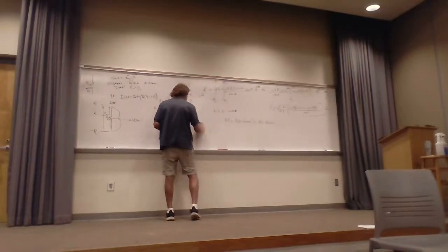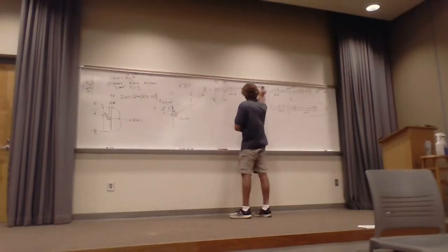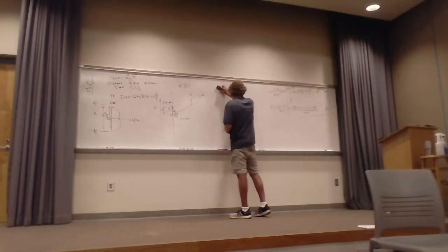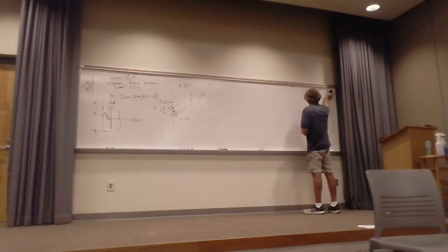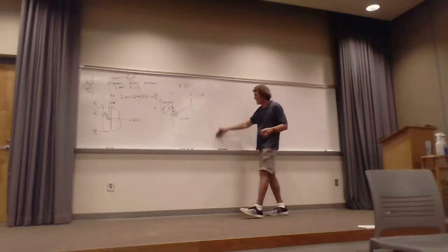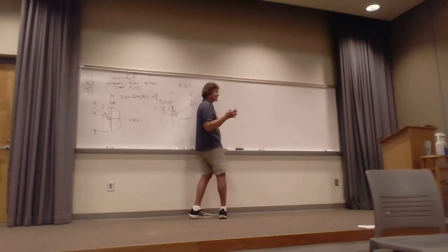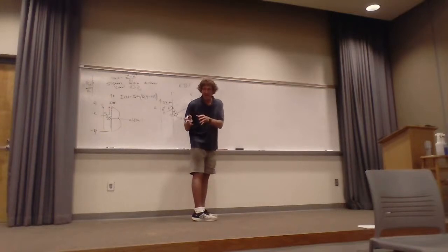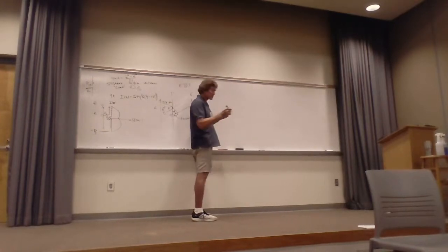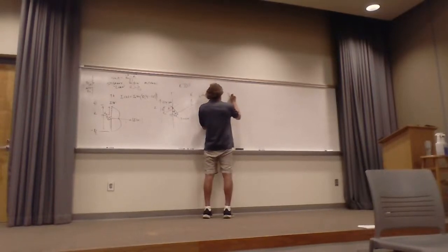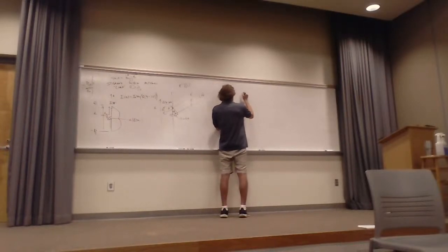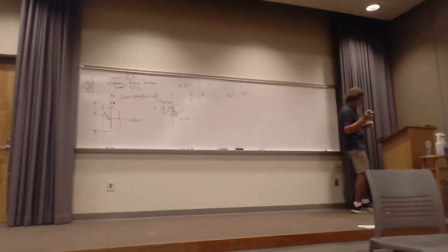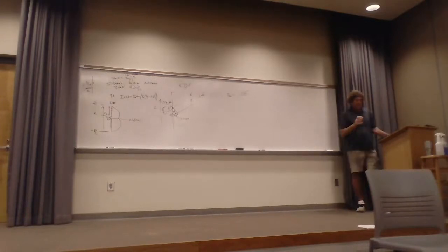So if I have this antenna, after you do the mathematics, I'll talk more about the ones we really use. So if you have this, there's one thing that's important, it's the average power density. If you got that, you have the E field, don't you? Right? So his book shows you this. Put it down as PAV, from an arbitrarily long antenna, and he'll have it as, I think it's 15 I naught squared, over pi r squared.